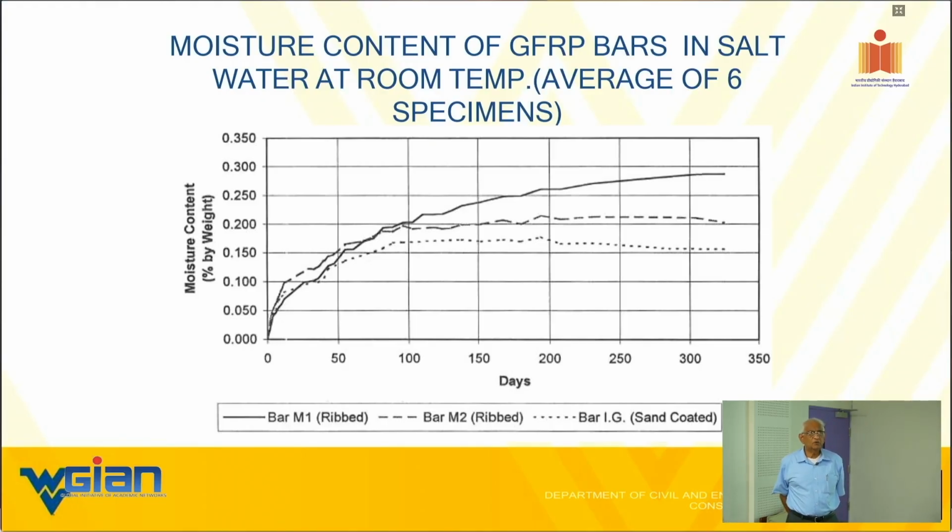So where would the moisture go? It goes nowhere except entrapped in the thing, which increases the diameter, which is equivalent to your typical corrosion issue of a steel bar. It's not corrosion, remember, but somewhat. The phenomena of how the concrete is going to behave is similar to that. That's the point. And of course, 0.15% effect is much, much less than 10% equivalent effect of steel due to corrosion. So keep all that in perspective.